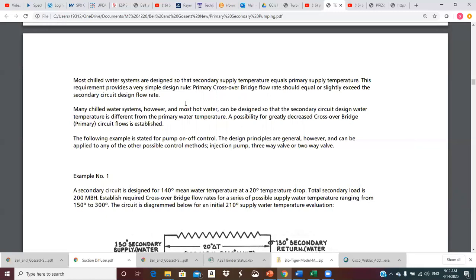And so we would basically pull that same primary water up and put it into the secondary. There would be no mixing at a T or anything. If we can get 44-degree water out of the primary into the building, we want 44-degree water circulating up through the building through the coils, so that they will dehumidify as well as provide sensible cooling.